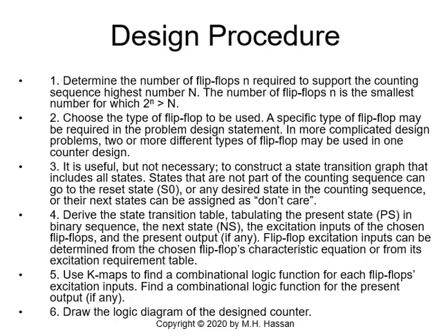However, we have to design them. We have to find the excitation input for every flip-flop, namely SA, RA, SB, RB, and so on and so forth. Or TA, TB, TC for T, triggered flip-flops, or JK flip-flops. So indeed, that is where the input excitation has to be driven.